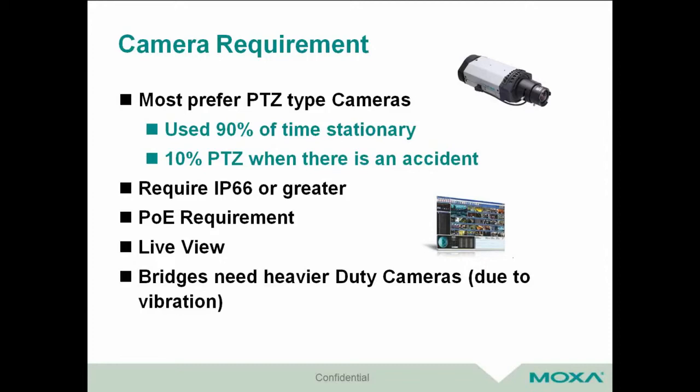One thing that I did notice is when you're putting these cameras outside in the field, there's a lot of shock and vibration. There's different applications, and you really want to focus on those certifications, because even though you're getting a camera at a very low price range, you want to make sure that the camera will actually last. In some cases, you have a camera fall apart because it's unable to take those vibrations. I would say make sure that you focus on the certifications that apply to the application so that you don't have a faulty camera within 6 months. You want it to last the lifespan you expect it to be, 5 to 10 years.